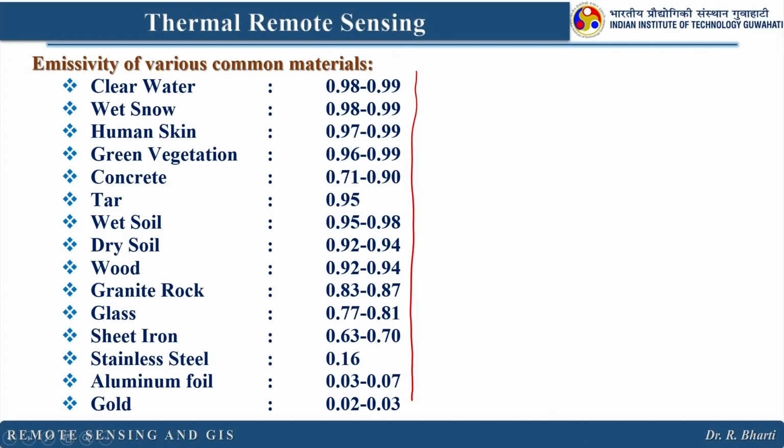So the temperature was the same, and we could not find out what type of material is lying in my study area. But as soon as you include this emissivity factor, you can easily find out what material it is. So again you can go to that signature level. You can use this as a signature because emissivity is a function of wavelength and material composition.